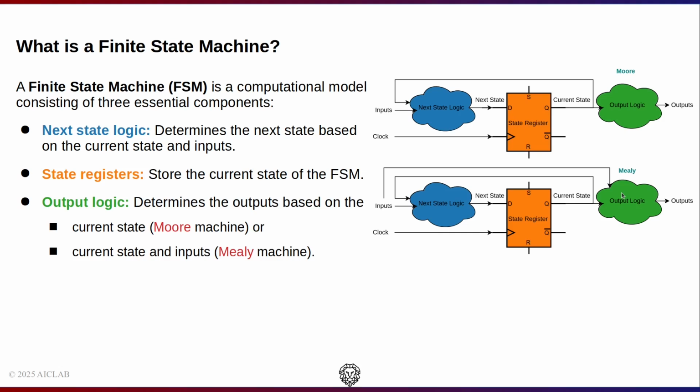If in your FPGA or ASIC design the output goes to an output port, it's recommended to register the output. In this way, the output glitch is reduced. And also in ASIC design, if you partition your design and different people work on different partitions, and the output goes from your partition to the next partition, it's recommended to register the output. So always use combinational logic for input and sequential logic for output. In this case, it makes writing the timing constraints much easier for your partition.